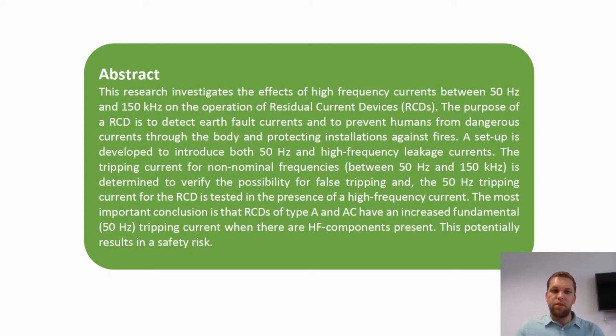And the most important conclusion is that the RCDs of type A and AC have an increased fundamental 50 Hz tripping current when there are high frequency components present. And this potentially results in a safety risk.